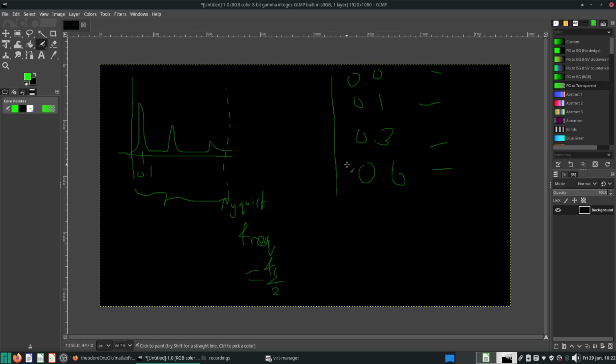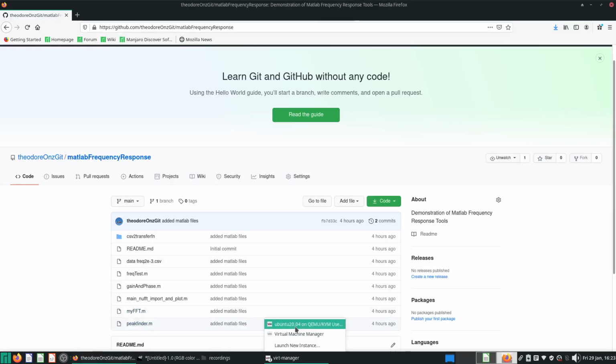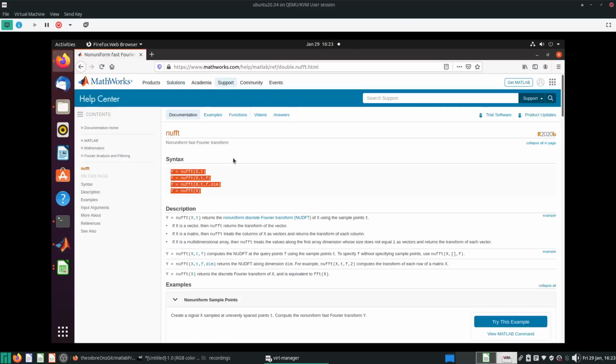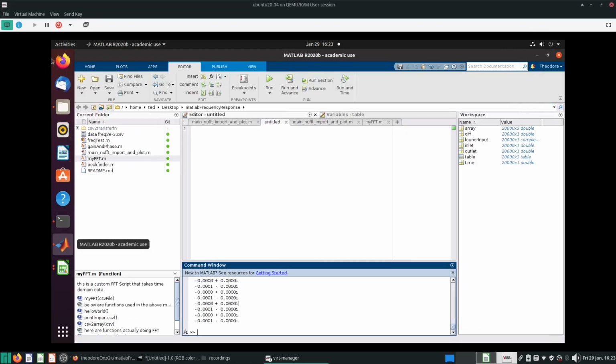Okay. And now how does the algorithm actually work, and how do you then determine which frequencies to plot your magnitudes of your Fourier transform against? Alright, so when you have something like this here, the standard way that this non-uniform fast Fourier transform works is basically to assume that you want to have your frequencies evenly distributed. Now, what do I mean?